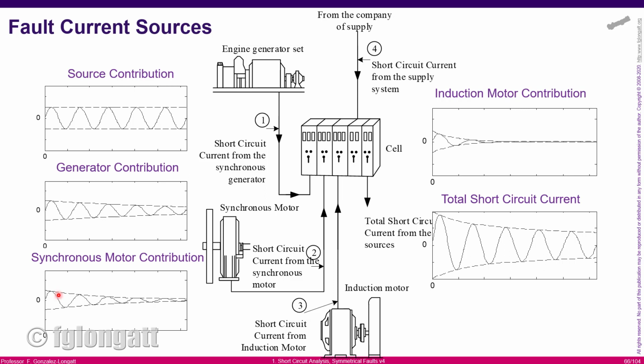The induction motors provide short circuit contribution. The contribution will depend on several factors. One of them depends on the size of the induction motor. Some standards say that motors below 50 horsepower are not providing contribution.